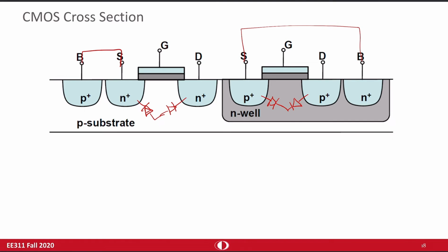A typical silicon wafer has a thickness of like 500 to 600 micron. It's like a CD. And all these dopings are happening in the top 15 micron. This is just an exaggerated drawing, but these dopings, N-well, P+, N+, are happening at the upper surface of this silicon disk.